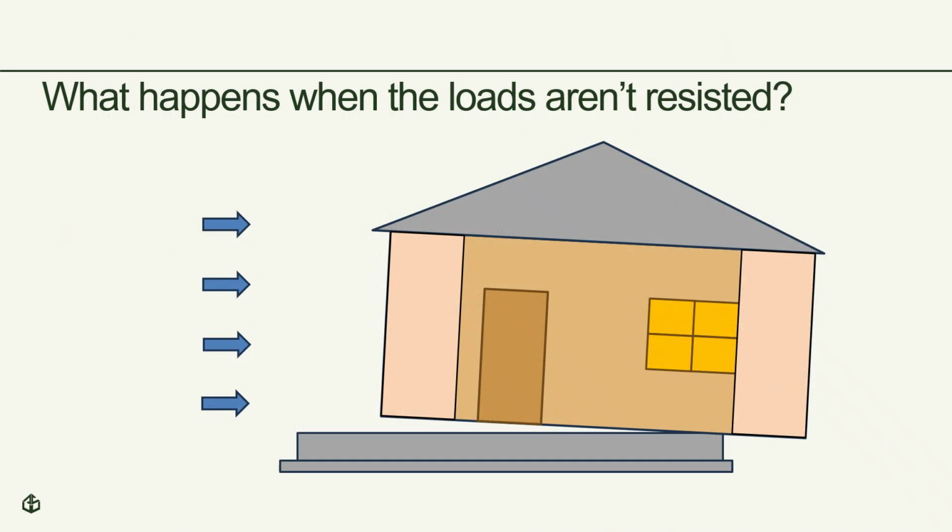So what happens if the building isn't properly connected to the foundation? Here you can see one possible failure by sliding. While clearly a concern in seismic events, there are real-life examples of buildings that moved as a whole off of the foundation due to wind events.